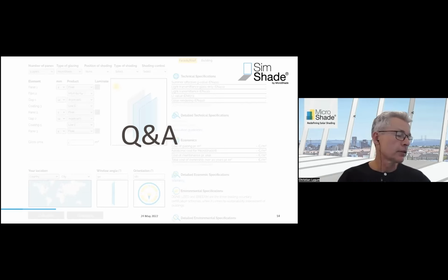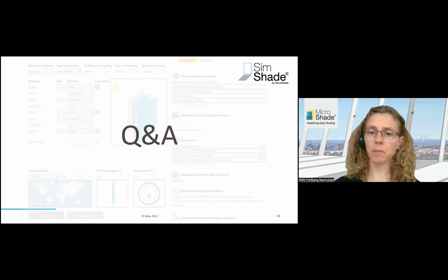Yes, I think this is a part of the next question as well, because if I used a coupled dynamic workflow, I can't get enough light in the building with solutions, I think. Yes, and this is probably because if you are used to doing daylight factor calculations where you do not take the shading into account, then of course once you apply it in the climate-based daylight calculation, the daylight availability will decrease.